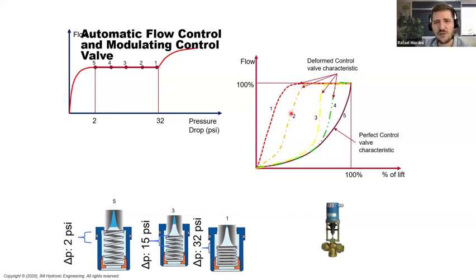I would say that these curves here, 2 and 1, are definitely worse than authority 0.25. This here doesn't work for modulating control at all. We should be using on-off here. Oh, but I really need modulating control. Well, unfortunately, in this case, we should be sizing your control valves better. That's not the subject here, right? We're just telling you that the balancing valves can't help you on that. Sometimes we have this false assumption that one balancing valve can fix controllability, which it can't, you know?